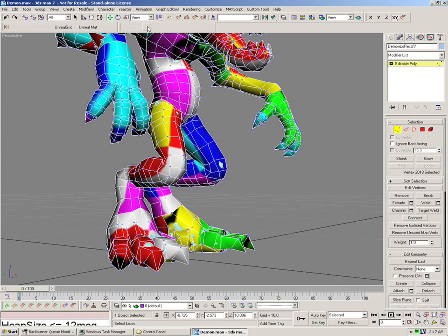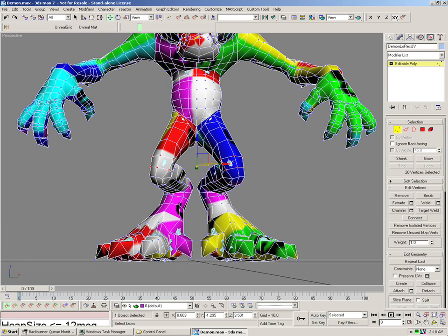And I've got a couple little scripts up here, although I don't have the icons loaded. But these are scripts that you can download from ScriptSpot, written by Bobo. We've taken them and modified them a little bit at High Moon. But basically what this is going to allow me to do is symmetrically select sub-objects in my scene. So for instance, you see if I select those two vertices, I get a symmetrical selection over here, so I can really quickly get symmetrical selections and edit things.